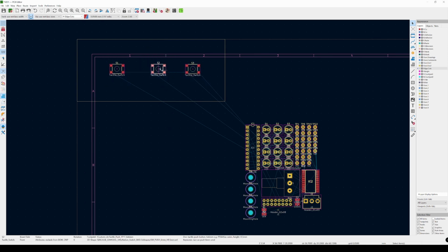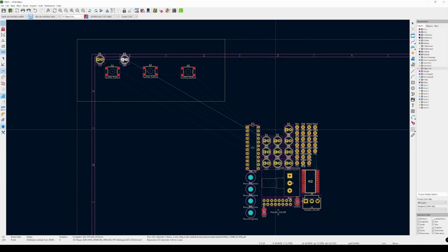If you are just creating a PCB without any specific placements in mind or specific requirements, this is gonna be way easier and you can do this way simpler. But what you wanna do is go ahead and put everything where you need them to be. So one thing you wanna keep in mind is when you pick these components, place them here. D5 is here, and then you might expect D6 to go here.